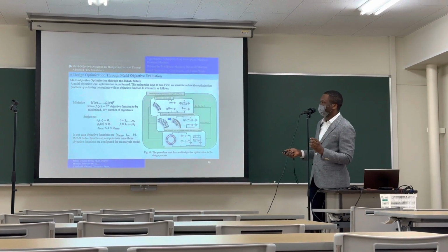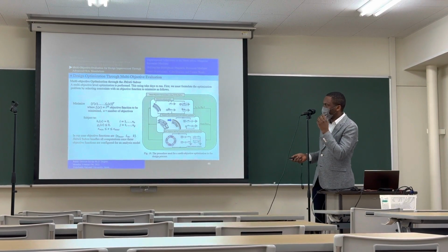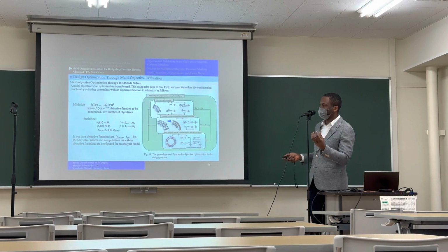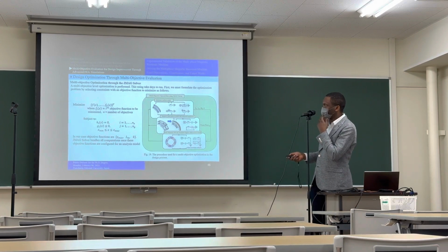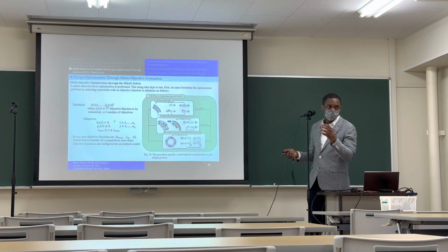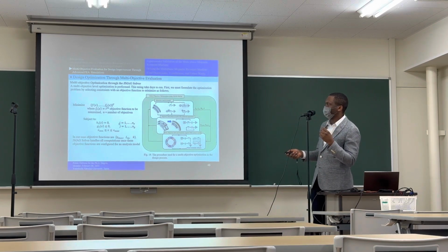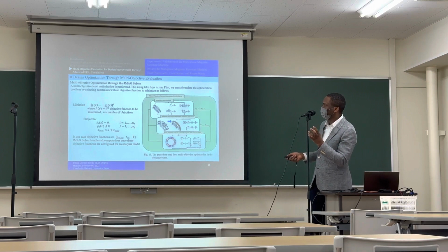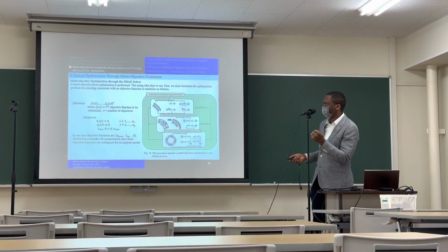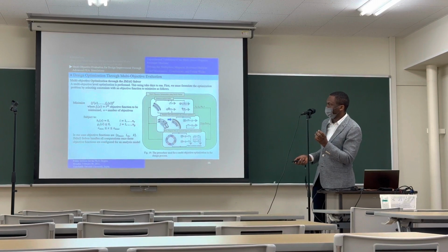But in general, when we do the research, we always use JMAG to do optimization because JMAG gives that computing power. What I always do is, first of all, on JMAG we can define some sort of objective function. The objective function can be, let's say, the efficiency. The main constraints would be the inductances that we want to calculate, like the self-inductances, mutual inductance, and the coupling factor. And then the main objective is to get the best resonance frequency and the best efficiency.